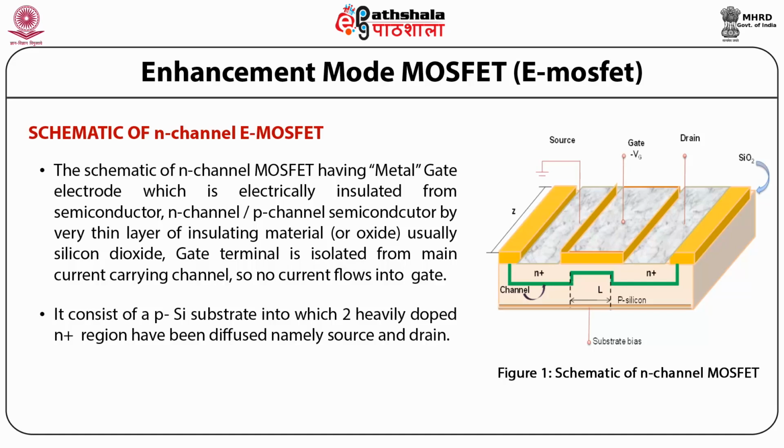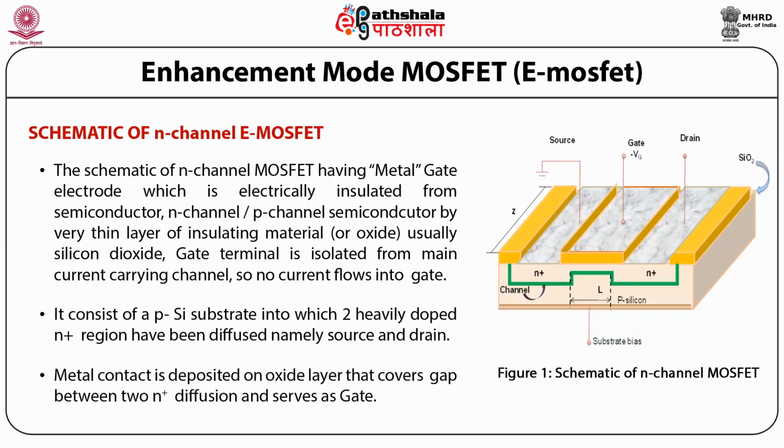They have been clearly depicted in this figure. A metal contact is deposited on the oxide layer that covers the gap between the two N+ diffusions and it serves as the gate.